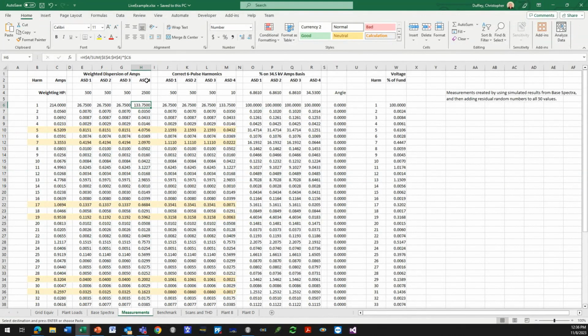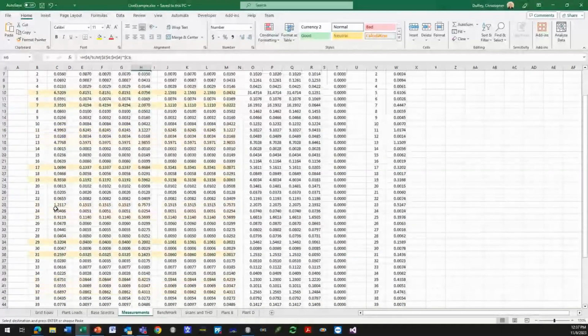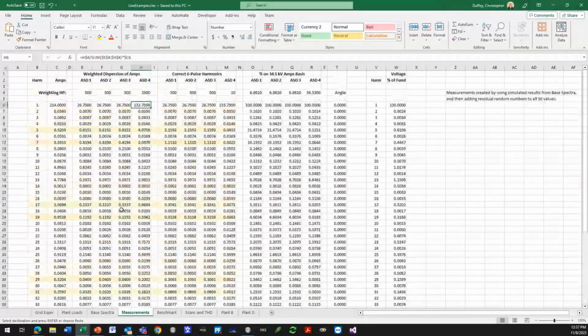So the 12 pulse content, or the 12 pulse drive itself, would significantly cancel 5th, 7th, 17th, 19th, 29, 31, 41, 43. And so I have to say, well, how do I take that into consideration? This is how I did it. I said at the 5th, the 7th, 17th, and 19th, that in reality, it's like having 3 500s and then this one just being a really small drive because it only has residual 5th and 7th. And that's what I did here.